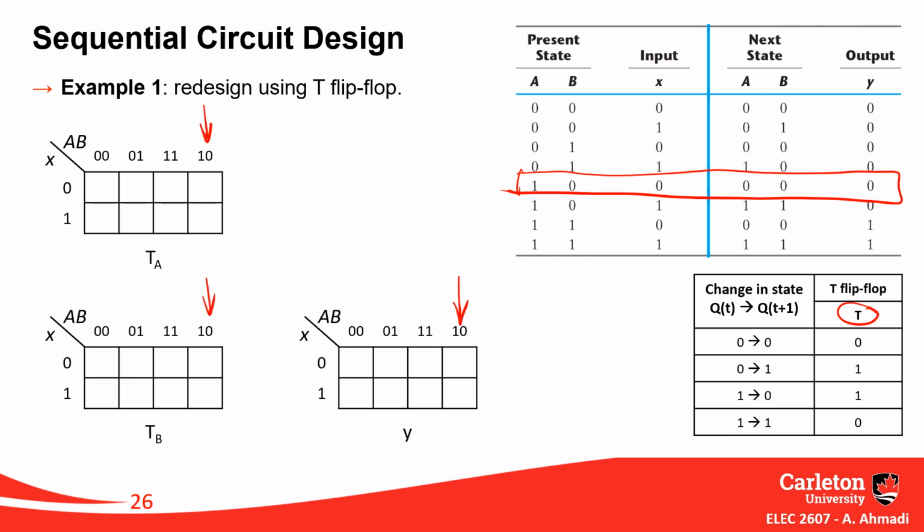right? For your current and next state at x equal to 0. So we are talking about this cell, and this cell, right? So A is flipped from 1 to 0, means you have to have, I'm sorry, here. You have to have 1 here, but no change in B, so B will be 0. And your output also will be 0.